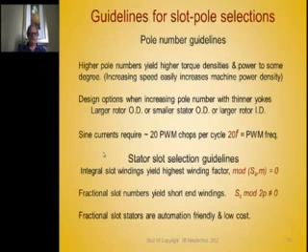Now we're going to study this later, but it's pretty well accepted amongst inverter designers that to produce a decent sine wave, they need about 20 PWM chops per sine wave cycle. So if they're limited on the PWM frequency due to the losses that are acceptable in the IGBT bridge, then this can have something to do with the decision of how many poles you pick.